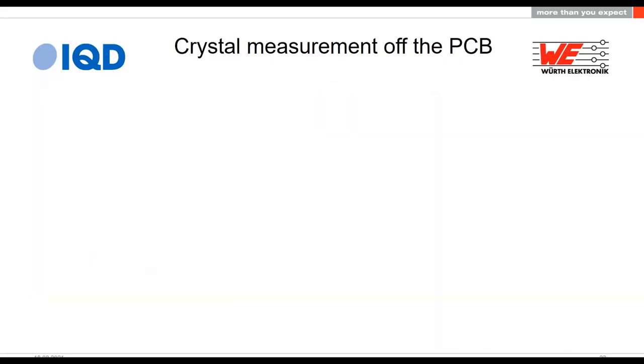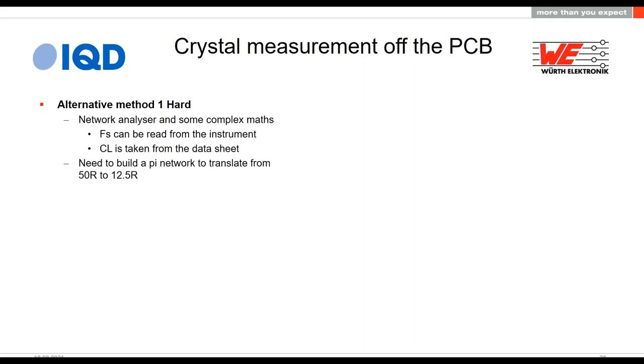The next measurement that we made was to measure the crystal frequency when it was off the PCB. You remember I took it off and I used that network analyzer with all that special software on it, and it gave me all those lovely readings which are exactly proportional, relatable to the crystal data sheet, yeah? How would I do that if I didn't have one of those things?